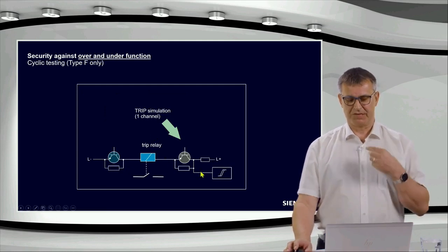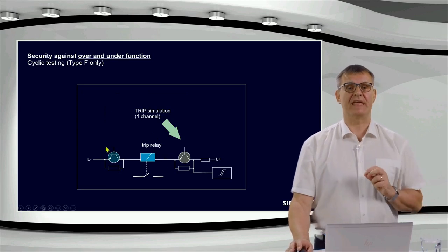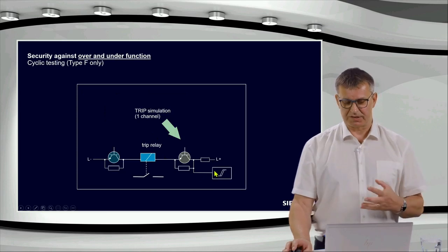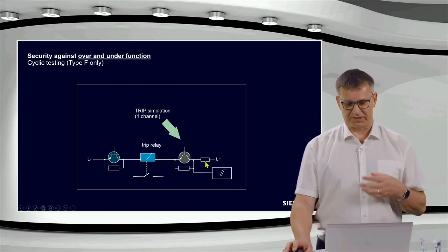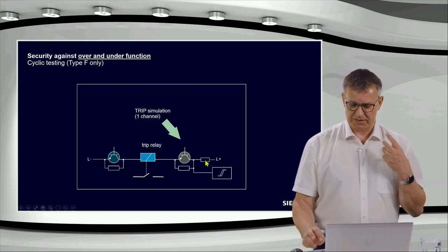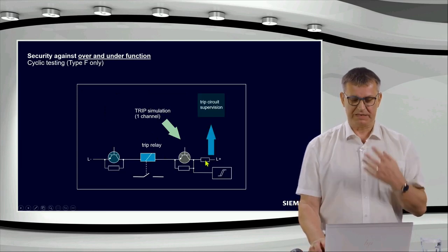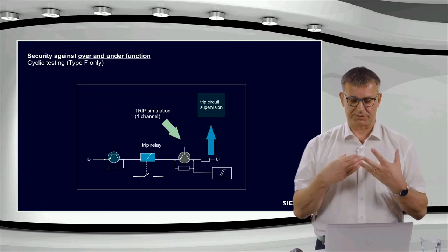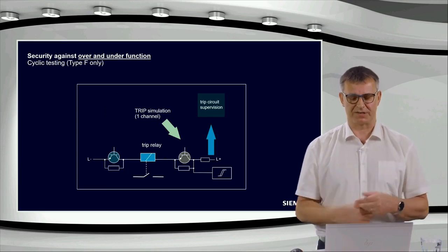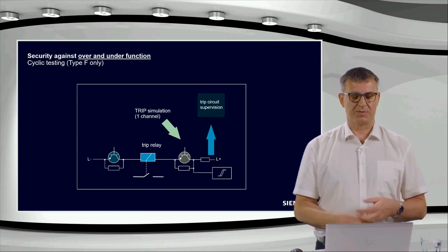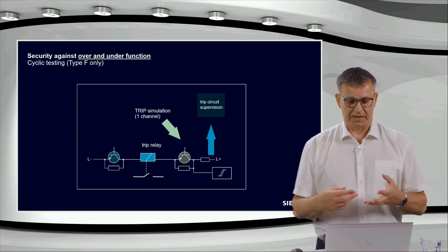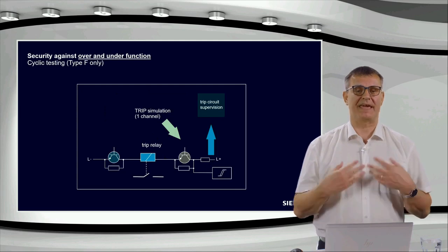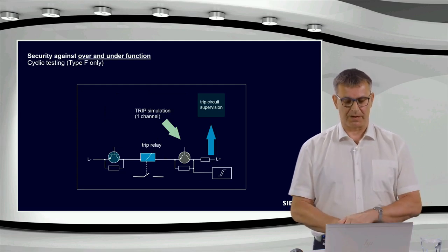Here we have these resistors, and this 1-channel activation will lead to a change in the voltage and the current, which can be measured, and then we can detect whether our trip circuit is working as expected, and otherwise we would get a failure. And we would indicate that we have a problem in our hardware by deactivating our binary outputs.